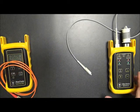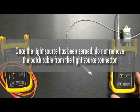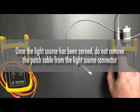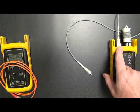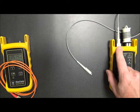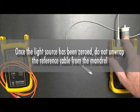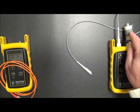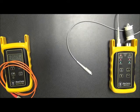Now, one thing I want to make note of, specifically on the WaveSource, once you've zeroed out, you do not want to disturb this connection at all, because if you disconnect and reconnect, you're not assured of getting the same reference level again. So if you do disconnect, you may have to re-zero and start your testing all over. Likewise for the mandrel wrap, you want to make sure that once the cable is wrapped around a mandrel and you've set a reference, do not let this cable unwrap from the mandrel. Otherwise, again, you will have to re-zero and take your measurements all over again.